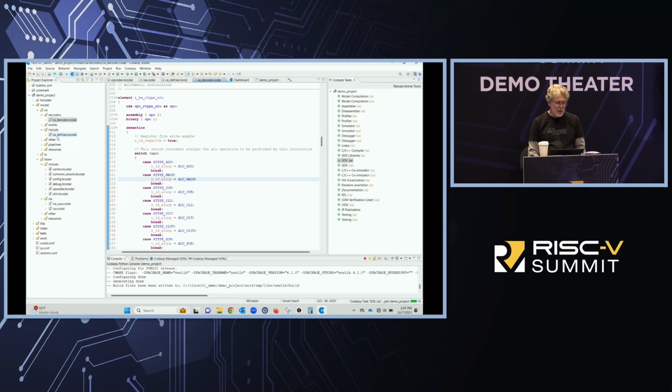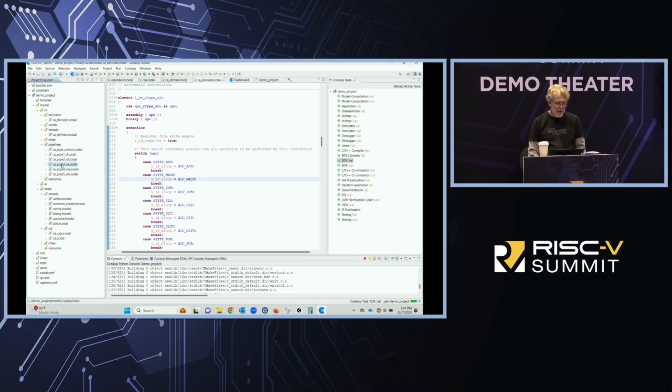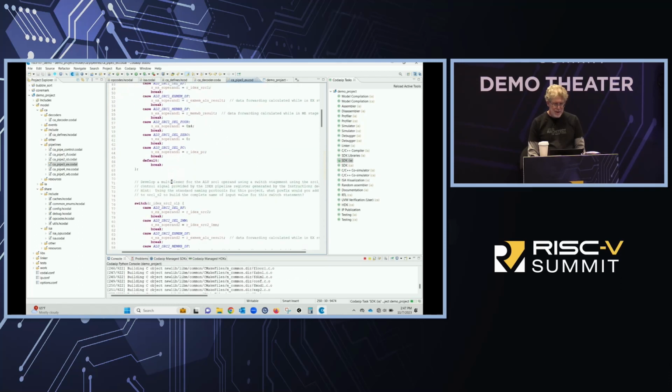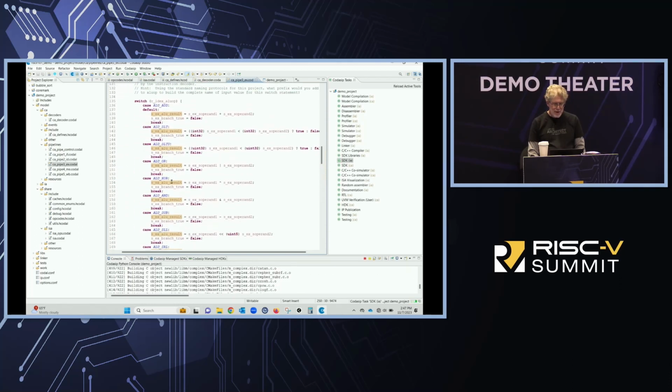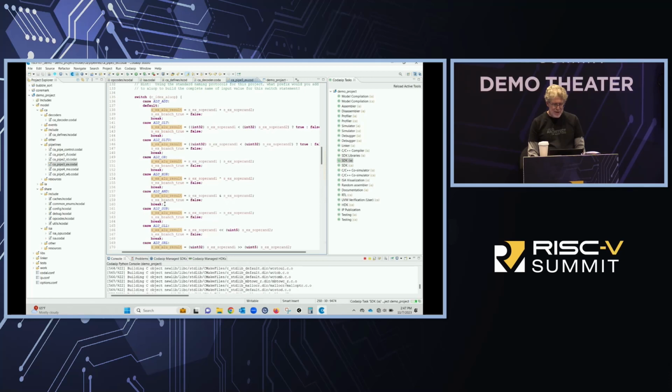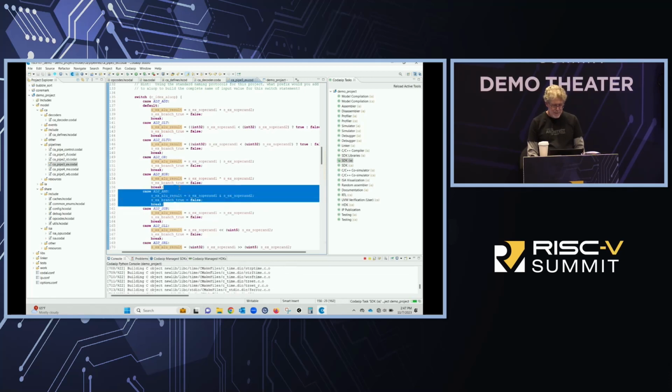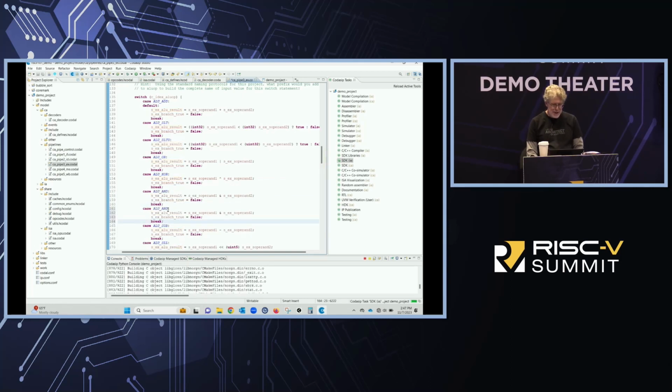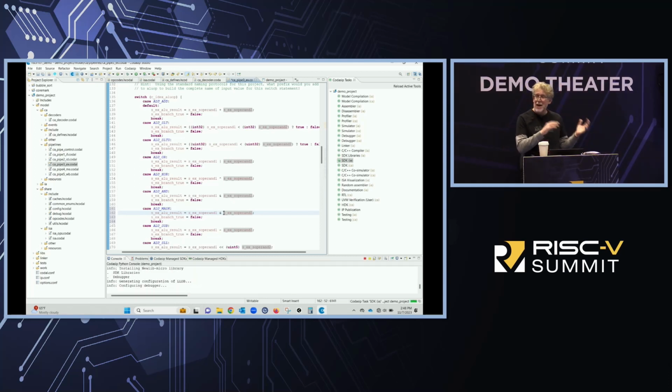The third thing I have to do is come down and actually add it to my ALU. I come down to my ALU here. Here's an AND, so it's very similar to an AND. So cut and paste. Now I'm going to say the micro opcode is mask. I have to make sure that what I tell the ALU is exactly what I told the semantics for the instruction set. So it's going to be AND minus. They have to match. So I've now finished the cycle accurate model. This will generate the RTL that you need to actually run your code.